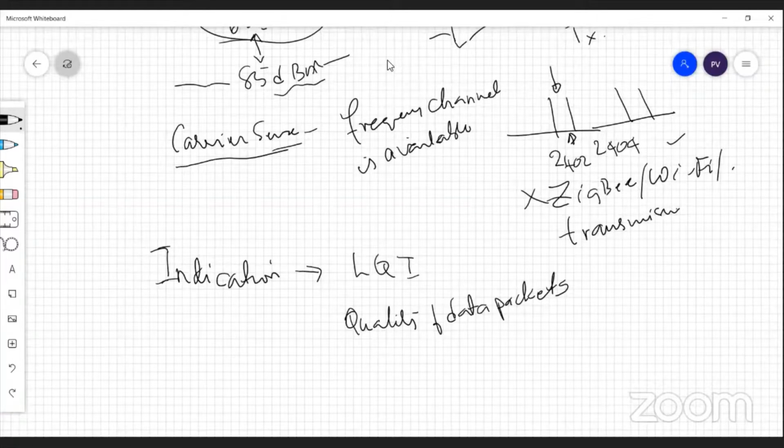So the link quality can also be judged using both signal energy as well as the signal to noise ratio. You can use both. These are some nuances in the LQI, and you do LQI on a per packet basis. This is very important. Unlike RSSI, which collects some symbols and then averages them, you do this on every single packet, and it is reported back to upper layers and so on.